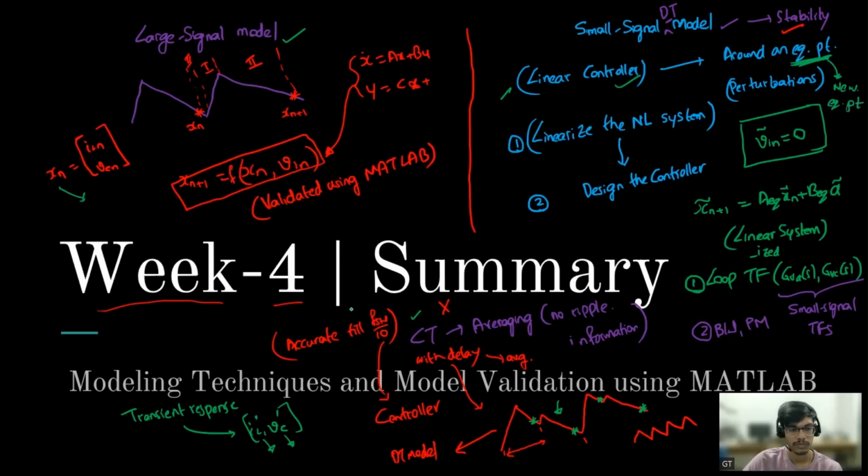Understood? Sir, will small signal modeling be able to work in transient conditions too? Yes, actually it is not designed for very high steps, but as far as small steps are concerned, it is okay. But still there will be a limitation in the small signal model because it has less bandwidth, for which we should go for large signal tuning.